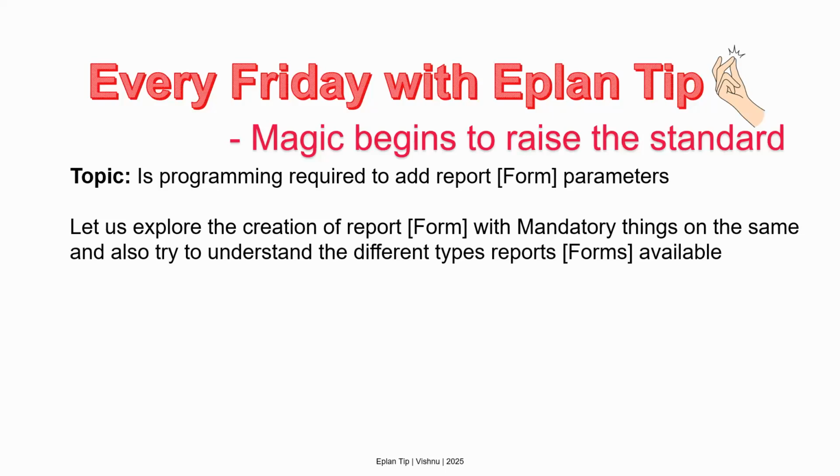Before we start, I also want to tell you that first you should know what a form is. Remember that when I talk about a report in Eplan, the terminology you need to know is form. You have some 40 different kinds of forms available, but it all depends on the kind of project you do. At least you should know that some 5 to 6 different kinds of forms can be created, but it all depends on the kind of project you do. There is no limitation on which forms you want to create in Eplan.